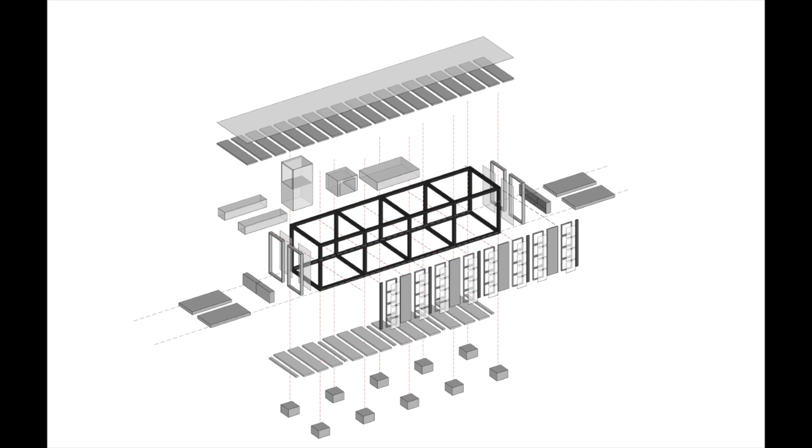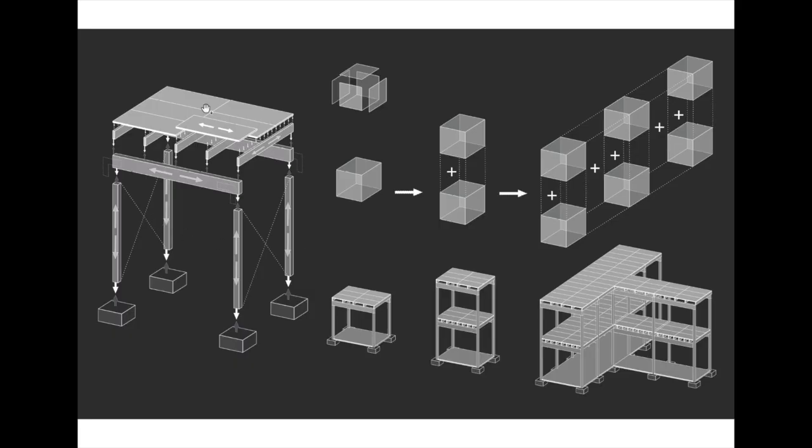When you start to establish a structural module, this module then can be used as other planning things. Planning not just for doors, windows, floors, foundations. Once you stay on module, everything else tends to find a good, consistent answer in terms of what its dimension is. Structurally, it also helps you as well, because you can start with this basic idea that there's load collectors: deck, purlins, girders. Those load collectors go to load grounders, in this case columns, foundations, and then are stabilized with load stabilizers: diaphragm, X-bracing.